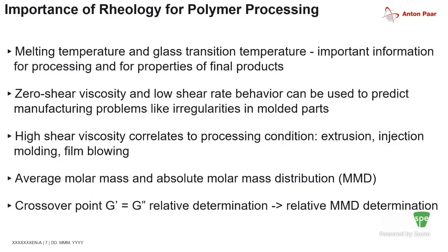Taking that into consideration, why is rheology important? If we want to understand the melting temperature, where the sample transitions from being elastically dominated to liquid dominant, we can look at the melt behavior, or at the glass transition temperature, where the moduli become constant over a range of temperatures. This is important from a processing standpoint because it helps us understand where we can get the sample to start moving, and also its final product behavior.